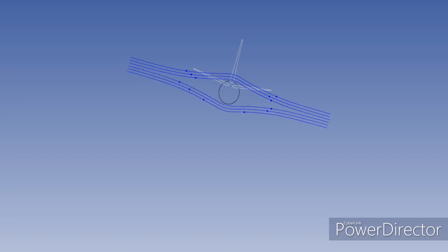As the aircraft side slips, the relative airflow is from the side, which we can replace with a view of an airflow stream. We can see that the airflow path is partly over the top and partly beneath the fuselage. This airflow is around the fuselage where the wing is attached.